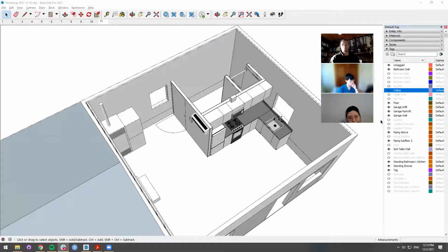Does that imply for us that if, let's say, the average concrete garage floor has a 1/8 to 1/4 inch per foot slope, that from a user perspective, you might just live in that space with that amount of slope that was never corrected for at the full floor plan level? Yeah, that's the way I would view it, in terms of the hassle of trying to make a level floor.